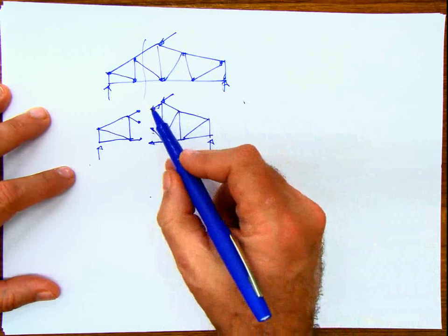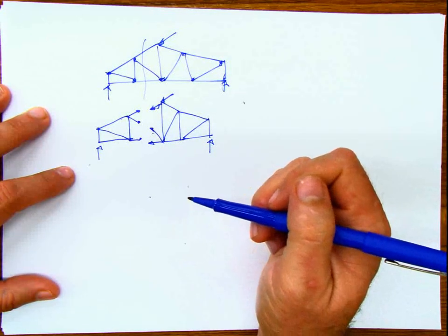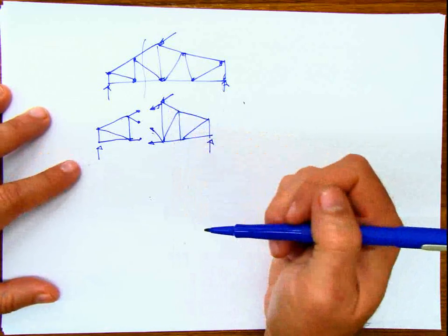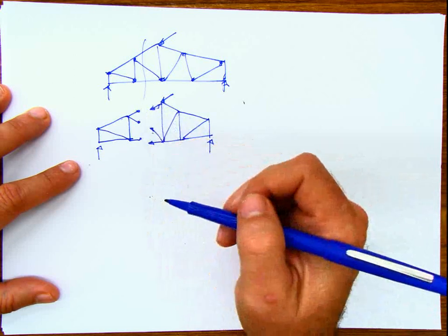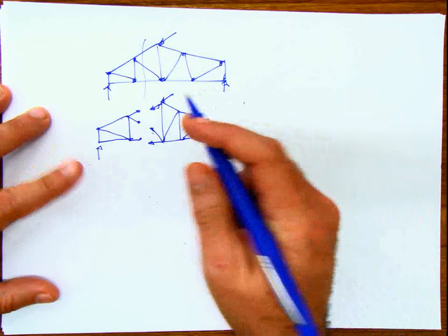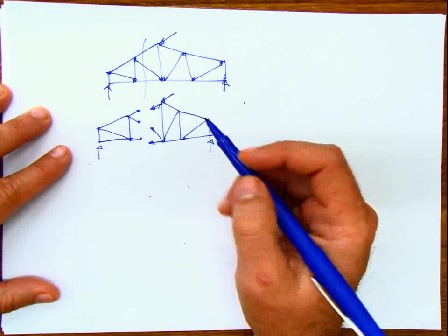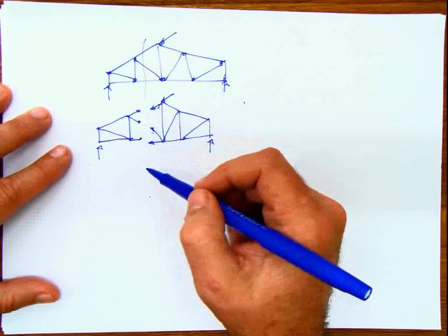But that happens only in trusses, or mainly in trusses. Why? Because of all the constraints that we have: no forces along the elements, just at the joints, smooth beams. That makes them kind of a two-force member, and because of that the forces are only tension and compression.